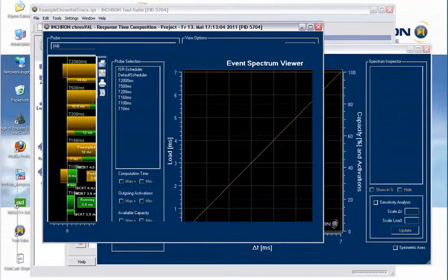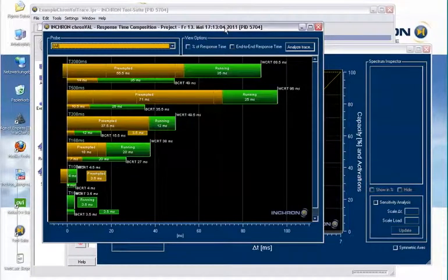The easiest one to understand might be the response times shown in bars. So what we show here is that you have these bars for every process that you have in your system, and the length of the bars depicts the worst case response time for the thick bars, and for the thin bars, it's the best case response time.